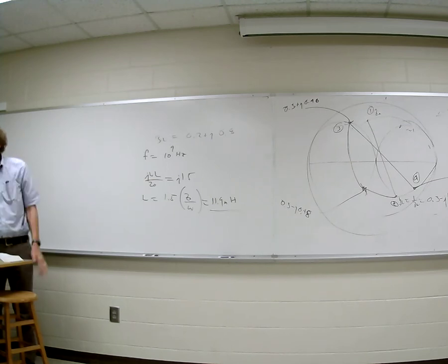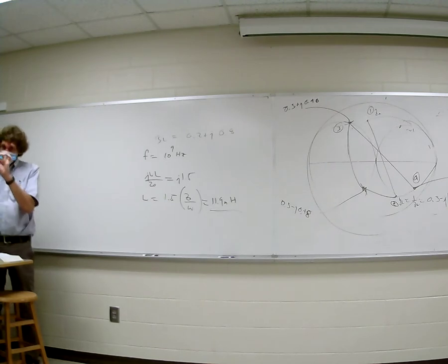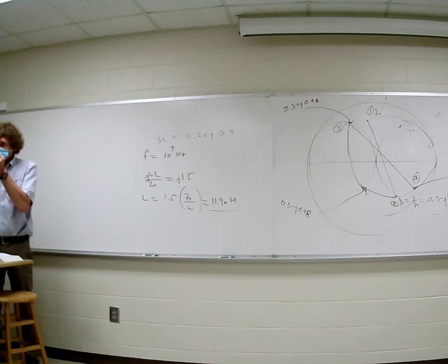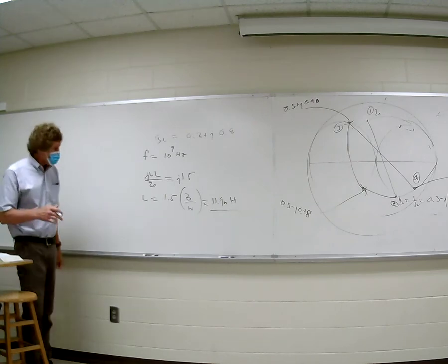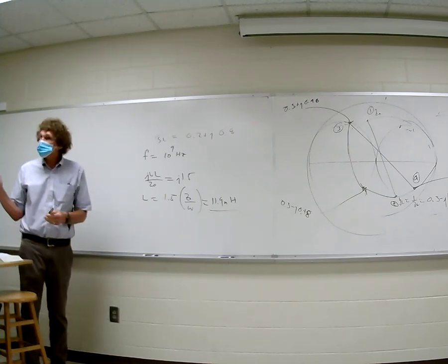So what you'll do is start adjusting the lead length until you get exactly half that voltage. That's the trick. When you have inductors, you'll have a small coil of wire, then you'll have these leads. If you just measure the full inductance with the leads, it's going to be greater than the actual inductance. Chances are much greater. Then you have to start cutting down the lead length a little bit, but you start small, and that's how you do it. All right, any other questions about this?